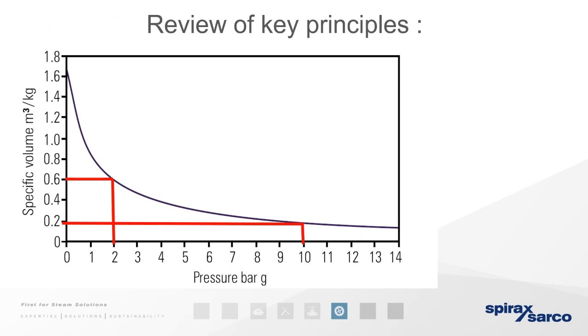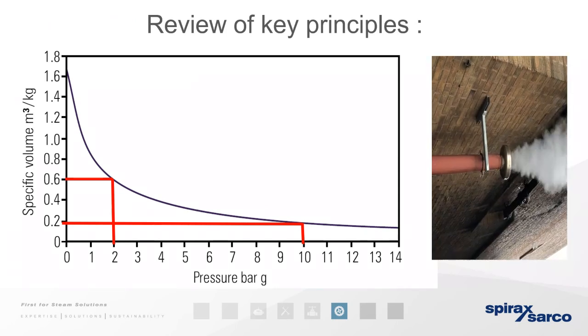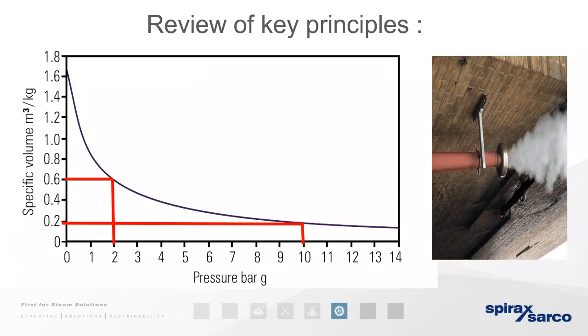So when the condensate falls in pressure as it passes across the steam trap, there will be a sudden fall in pressure, resulting in the excess energy being converted from sensible heat back into total heat and causing a rapid expansion and a change of state back to what we call flash steam. That is what we will see from the video as you see now.